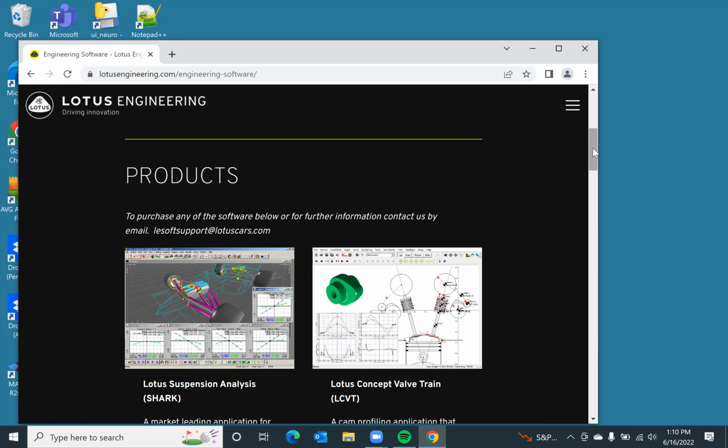And this is very important if you are driving a Honda engine, i-VTEC engine. They have two different valve profiles. One valve profile opens and closes the valve at low speed, and another profile opens and closes the valve at high speeds. That is needed because you don't have enough time for the charge to enter the combustion chamber when the engine is running at high speed. So you need to open the valves for a longer duration of time.